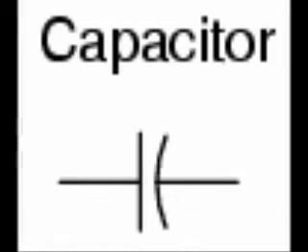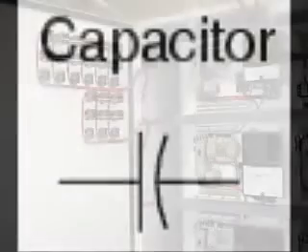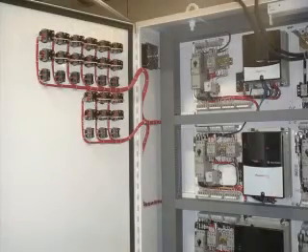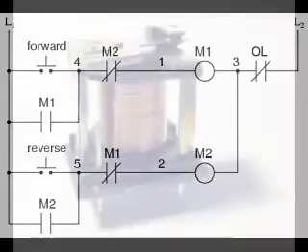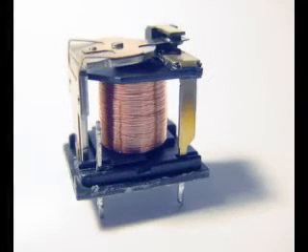All of these control switches and more are used in machine control applications. In years past, control switches have often been used with relay control logic. Relays are electrically operated switches. Relays are also called electromechanical switches. They are basically one or more switch contacts, often with both normally open and normally closed contacts, operated by an electromagnet. Relays are found in all sorts of devices.